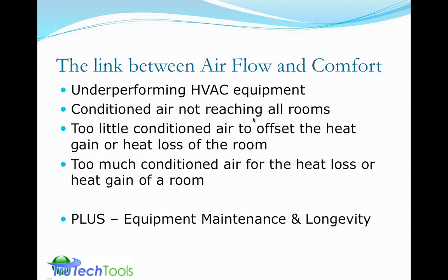Plus, most equipment is designed for a range of airflow throughout the system. If the system isn't receiving the correct amount of airflow, it can severely affect the equipment longevity, how long it stays in service, breakdown, things like that. I'm pretty sure most of you have heard about maintaining your filters. It's a very basic thing. You probably know people that have had that happen to them. I do, where a filter blocks up, chokes the airflow on a system, and may cause, say, a furnace to overheat, or an air conditioning coil to ice over because it doesn't have the correct airflow. So these are the kind of things we're talking about, and everything really ties back to the air.